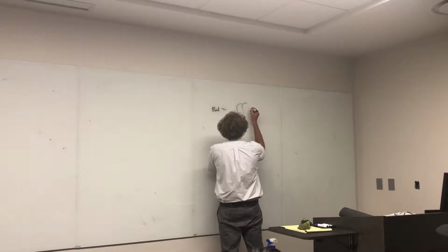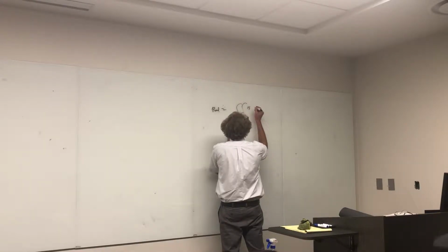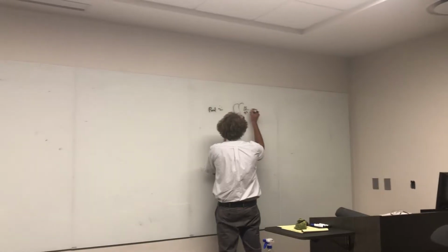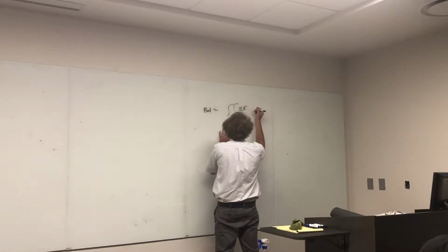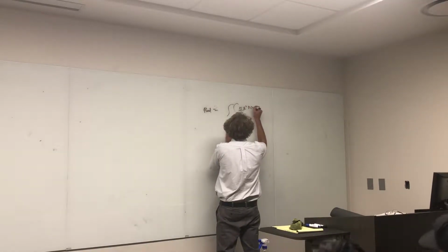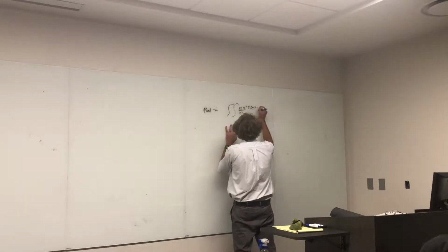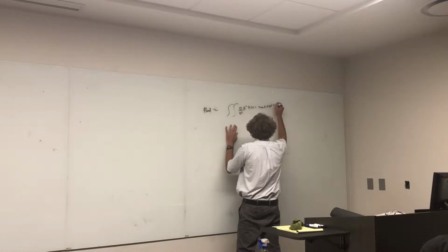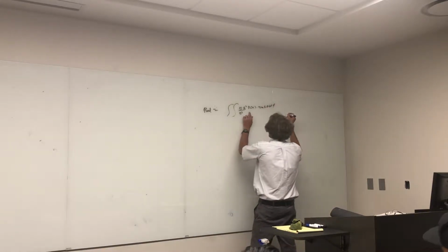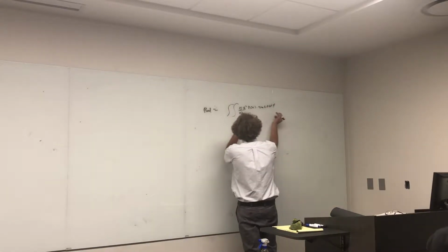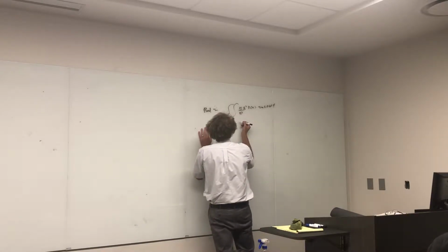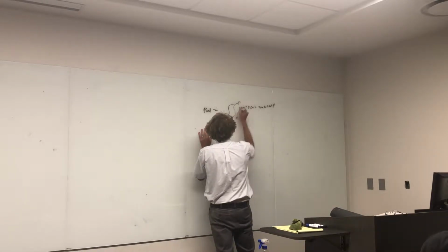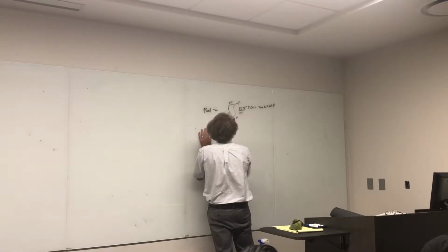He likes to use the normalized power, but you can actually take the power radiated, and that's 15 over pi squared, I naught squared, times that F of theta, I'm not going to put that in there, times sine of theta, d theta, d phi, and the r squareds will cancel, so I don't need to show. Theta goes from 0 to pi, phi goes from 0 to 2 pi.